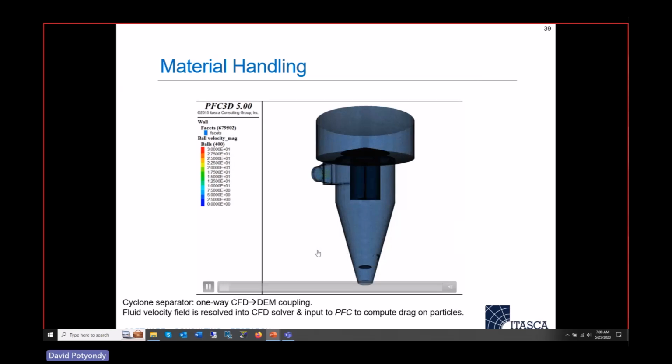So we've got fluid now interacting with the particles, and you can see them flying around in the air here and interacting with the sides of this thing. This is an example of coupling with a fluid dynamics code to provide the fluid flow field, which is then producing drag forces on the particles. Meanwhile, the particles are affecting the porosity in the cells of the fluid model. This is an example of a disperse assembly of particles getting dragged along in a fluid.